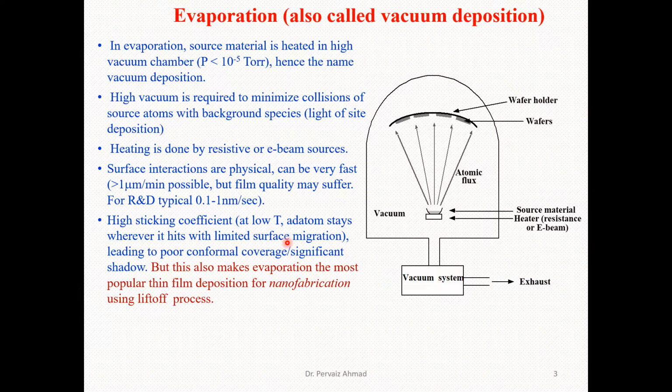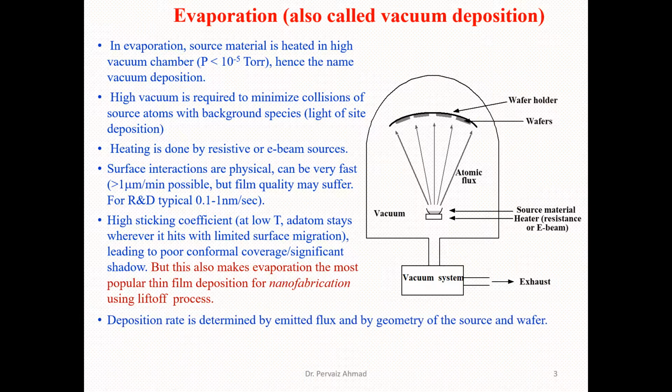In this technique we have a high sticking coefficient at low temperatures, that is, atoms stay where they hit, with limited surface migration. All of this leads to poor conformal coverage and significant shadowing. But this also makes evaporation the most popular thin film deposition for nanofabrication using the lift-off process.